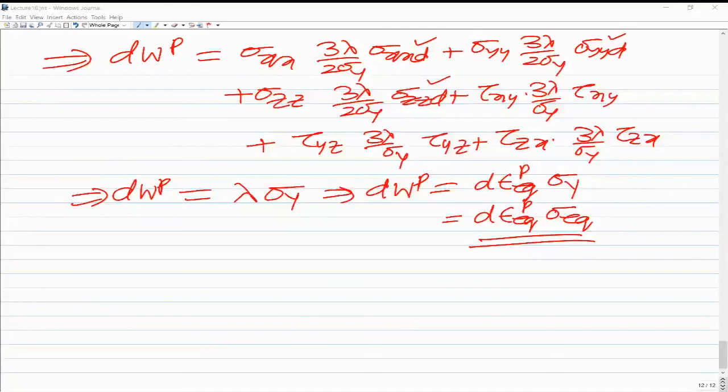Sir, when we formulate the KE matrix for the second, third, and fourth elements, will we be using the old KE matrix only, or will it be dependent on the x, y coordinates? As long as the element size is the same and the properties, Young's modulus, Poisson's ratio, thickness, are the same for all the elements, you can use the same KE. It would be the same for all the elements, with the local coordinate at the first node of the element.